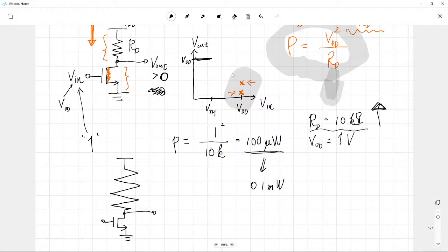Even in this case, when you apply VDD, your transistor is turned on, and since the drain resistor is so high, relatively the N MOSFET can provide a good path to the ground. So if we have a huge RD, we will have the output value quite close to 0.